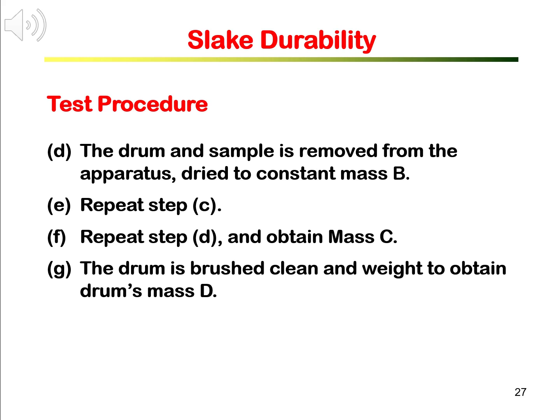The final step is to remove the rock specimens from the drum, brush the drum clean without any fragments inside, and weigh the drum. Record the net weight of the drum as mass D.